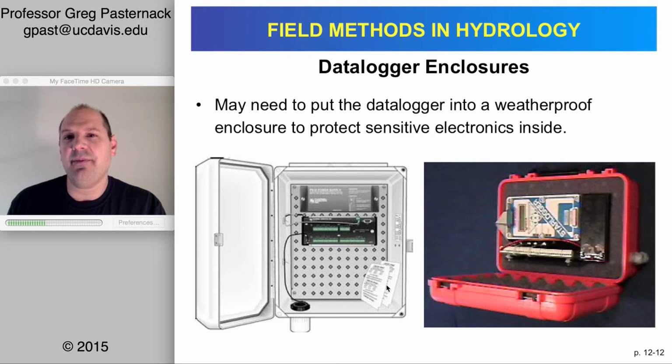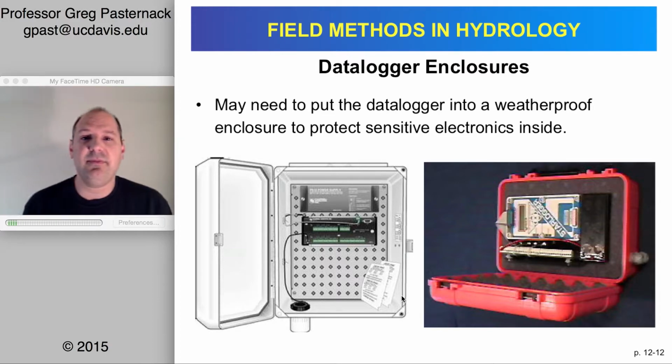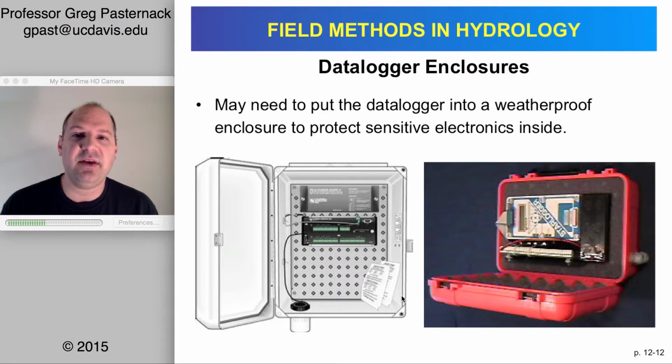And another thing you can see here, there are these weird little packages. These are packages of silicone materials that are highly absorbent of moisture. And so they just throw a couple of these packages in, and that way they will absorb moisture. Sometimes these packages can be reused: take them back to your lab or office or home, put them in an oven to dry them all out again, store them in a sealed bag or something, and then put them back in the enclosure. Other times they're meant to be disposed and just replaced.